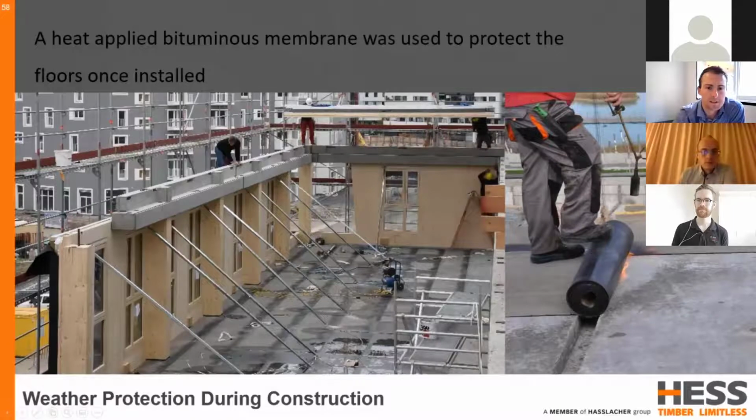So one particularly interesting item that I came across was the use of a heat applied bituminous membrane on top of the concrete floors. And this was applied as soon as the floors were completed, and it provided a waterproofing layer to protect the lower floors.